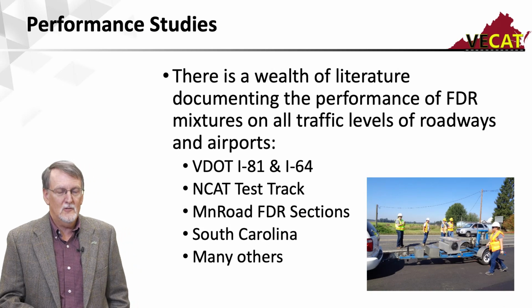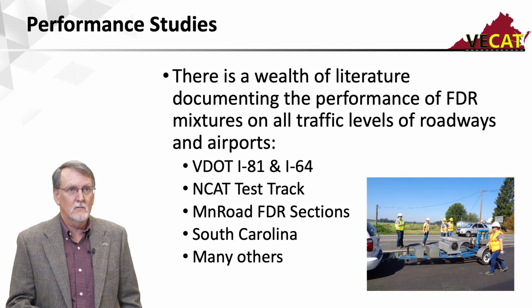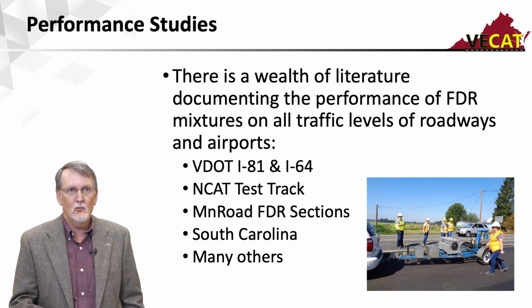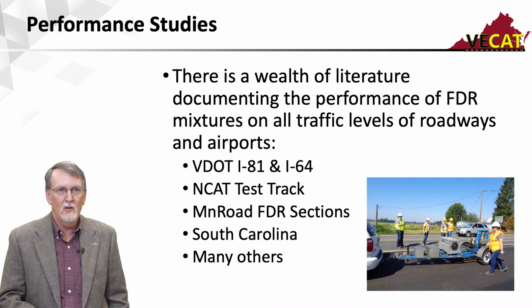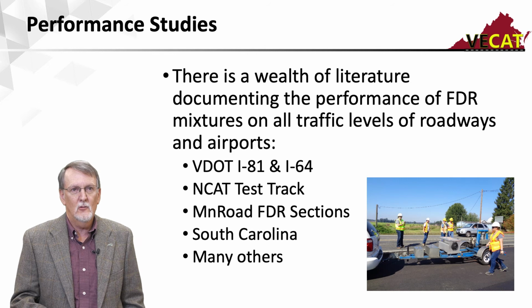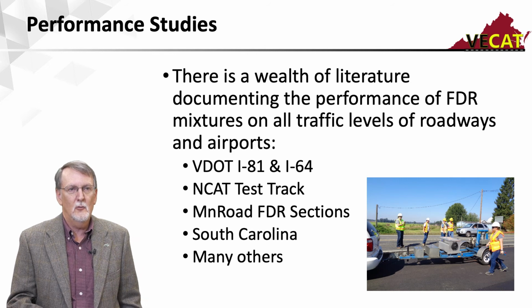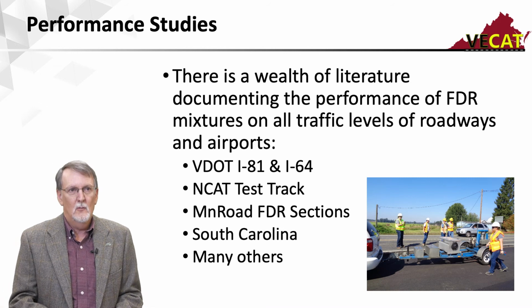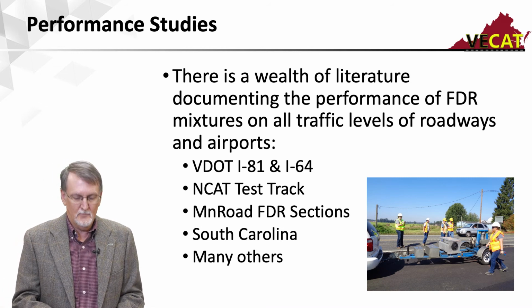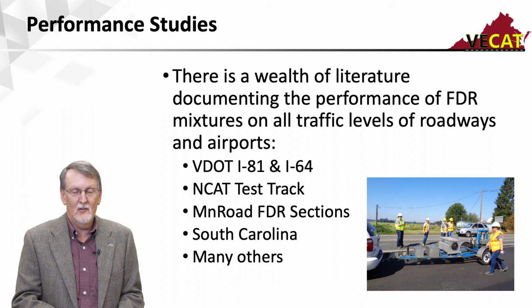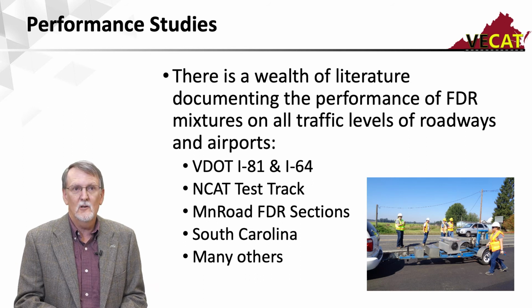As far as performance, again, there's plenty of information in the literature documenting the performance. It's been used on all traffic levels of roadways and airports. A couple we'll talk about. Virginia DOT used FDR on I-81 and I-64, and then they put down some sections at the NCAT test track. MnRoad has some sections up there for cold weather. South Carolina's probably done as much FDR with cement as anybody, and there's lots of other states that have experience with this as well.